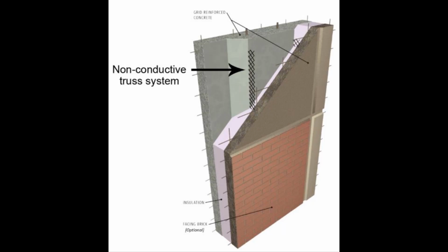Partially composite panels provide less than full shear transfer between withes. They behave in a manner in between composite and non-composite. The degree of composite action is determined by load tests performed by an independent testing lab. Proprietary partially composite wall systems are now available, which combine the high insulating value of non-composite panels with the strength and slenderness of composite panels. This is accomplished by using a non-conductive truss grid or individual connectors between the withes for shear transfer. Partial composite action provides sufficient strength for most applications.